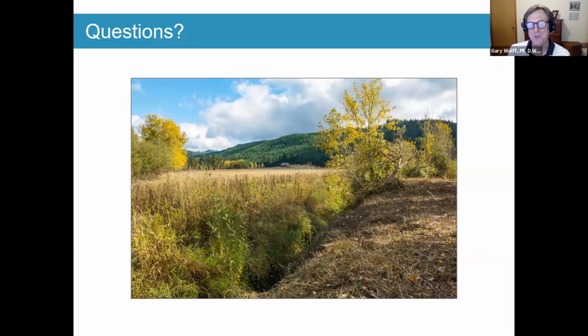If you just blanket come in and make really small elements everywhere, the run times are going to kill you. And that's why, like I showed, we made the elements smaller next to the bridge. And there's some guidance on what's a reasonable size, and we kind of followed that. And I feel pretty confident we have a good result.